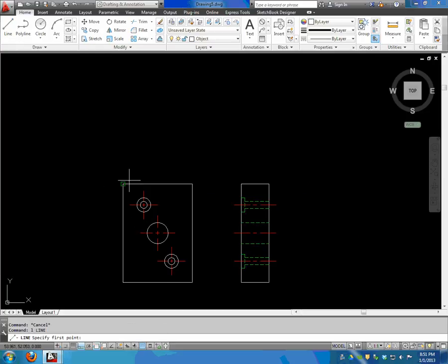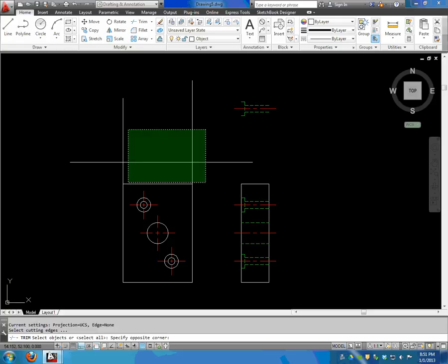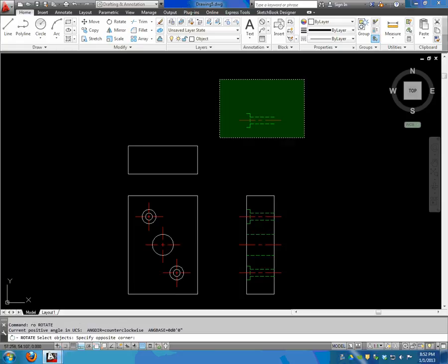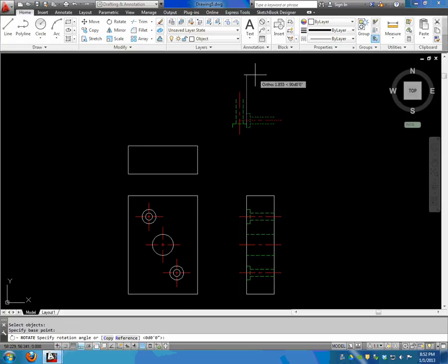Now we just need to do our top view. So let's just bring this up here. As I've hinted before, use what you already have. So let's do a copy. Let's bring this up here. I'm going to draw a line straight across. This is going to be our box. Offset, when I remember to use the button up top, 1. Trim, select this. There's our part. So now I'm going to do a rotate. Now I'm going to do a move.